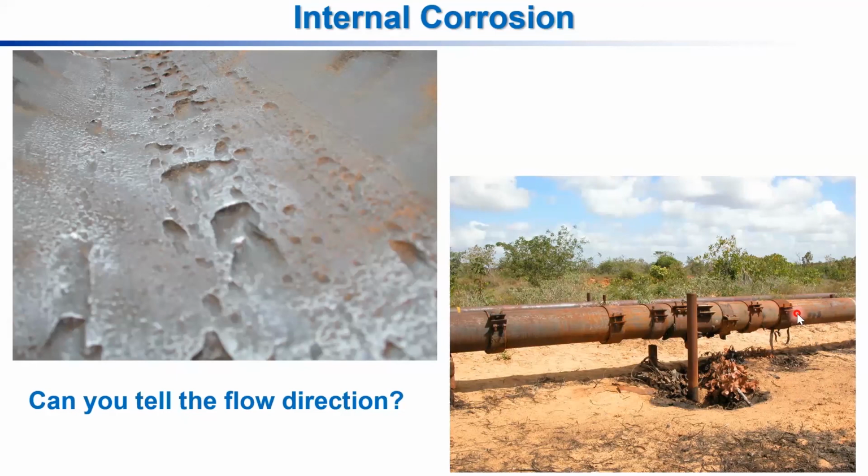A flow regime is how the gas phase, the oil phase and the water phase distribute themselves inside the pipeline. In this specific location, we had a slug flow. And a slug flow is one of the most aggressive flows in terms of corrosion. You would expect a lot of corrosion when you have a slug flow because of the high shear forces.